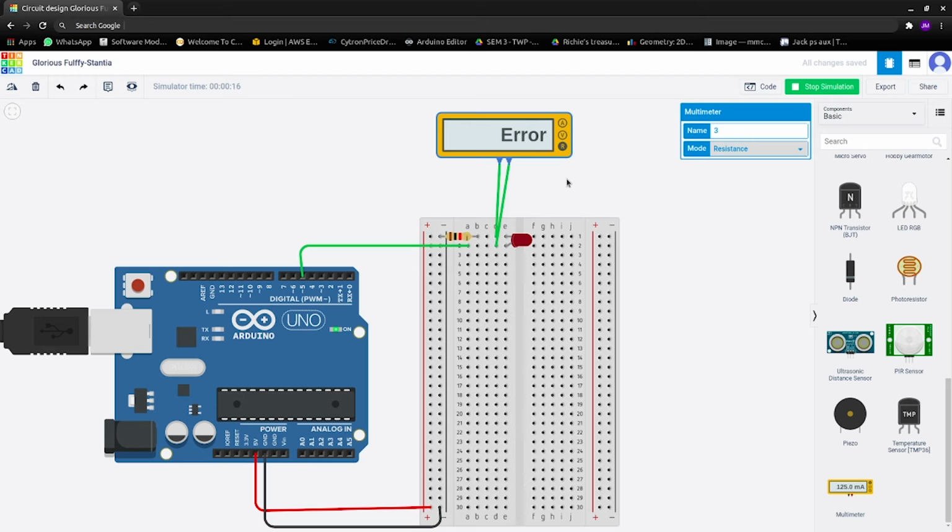Okay. We can also test the resistance here by clicking resistance, and we should get some error. This error here is caused by the resistance being too high and not being something that the multimeter can read. But as you can see, when it becomes in range of the multimeter, it suddenly becomes okay. And so we shall see more of this later when we try out the potentiometer.